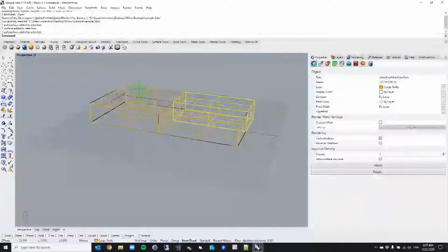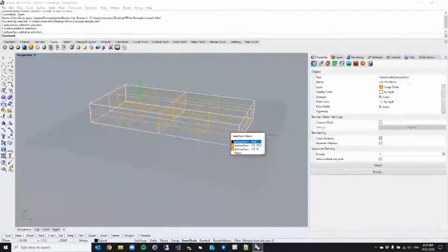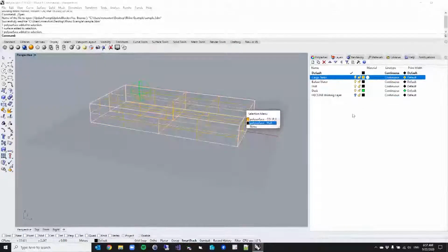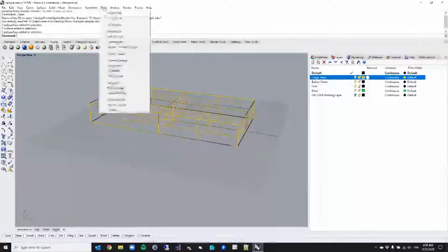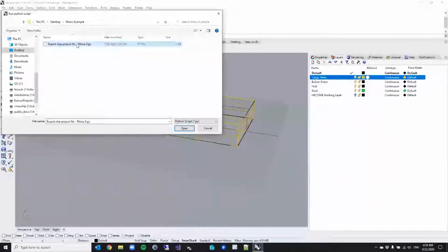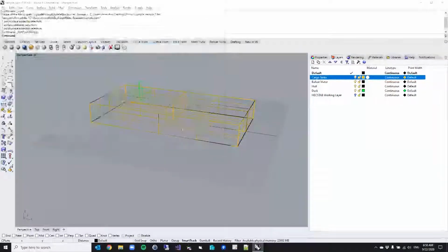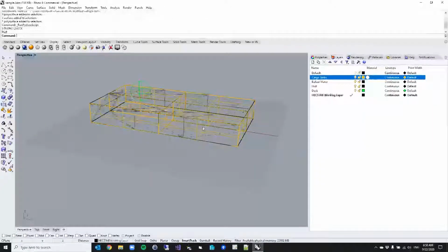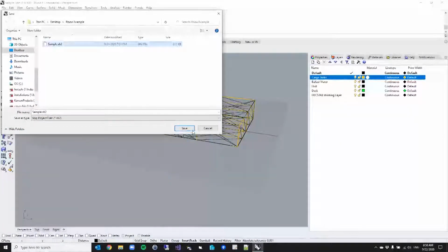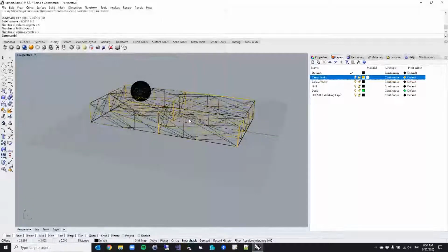But as long as I've done some basic modeling conventions in Rhino, i.e. closed surfaces, and if I do a little bit with my layers, if I add cargo tanks, I basically have my 4 surfaces here that are defined in my cargo tanks. Rhino has a tool to just run a Python script directly in Rhino. So we actually provide a Python script that you can run in Rhino that will export a ship project. And as long as you have the model defined right, as long as you have the layers set up right, you can create a model automatically.